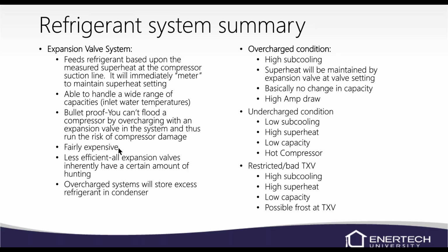Well, an outdoor split has a pump on it, and when it gets below 30 degree entering water temperature, it runs that pump all the time so it doesn't freeze. Yes, you do have antifreeze in it, but only down to 15 degrees freeze protection normally. And it got pretty cold this winter, and they left it off. The pump wouldn't run, and they froze it. So I get out there. I ended up finding the leaking flow center, and got that fixed.